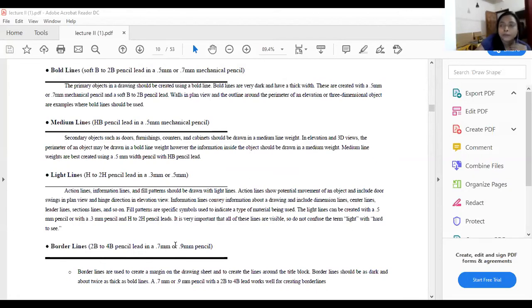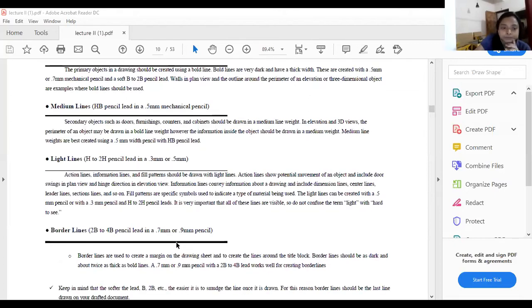So whenever you are preparing a drawing, you should always use layers so that you give different variations to your drafted plan, so that when the printout has been done, it is completely shown that the wall thickness and the interior wall thickness have a variation. So in that case, whenever the drawing has been sent to the site, it might be read by either a contractor or might be a mason. So he might not be confused about what is the thickness of the walls.